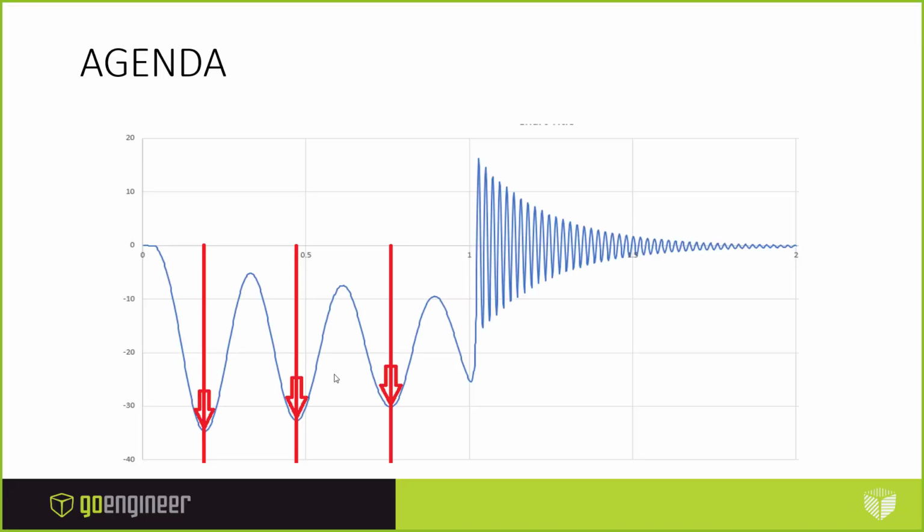Okay, so here's what I could do with this if I created a graph similar to the way I did in the linear dynamics study. Here's the kind of graph I get. It goes down and up, down and up. It doesn't tell me what the resonant frequency is directly. If my goal was to figure out resonant frequency using a nonlinear dynamics study, you can do it, but you'll have to do it a bit manually.